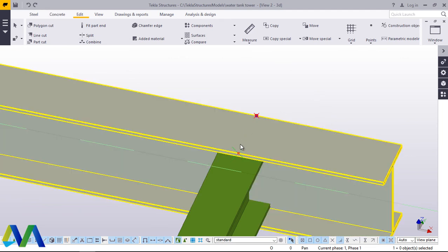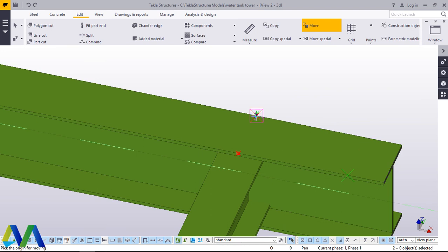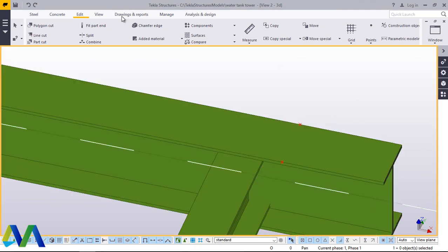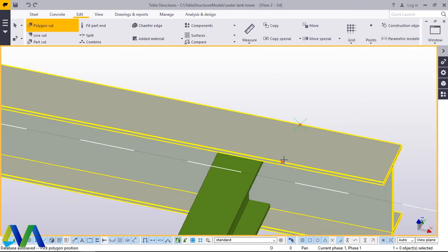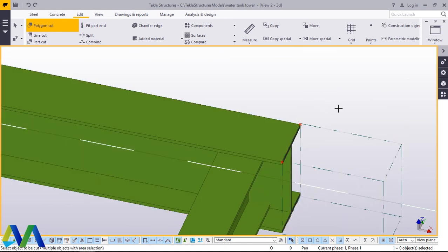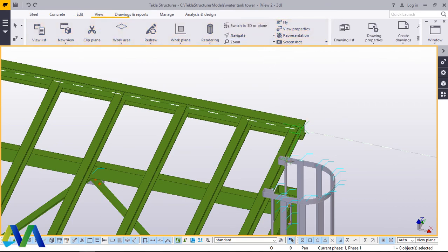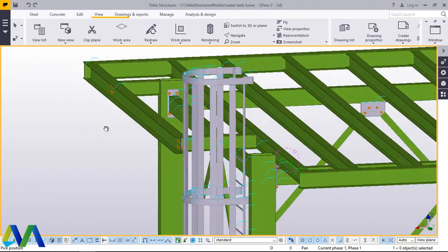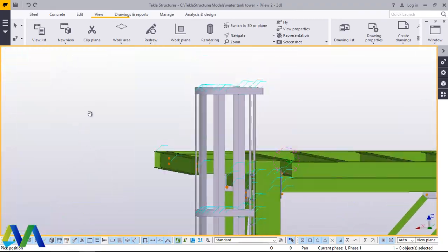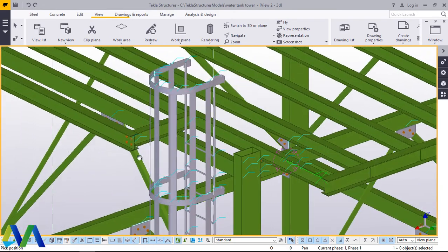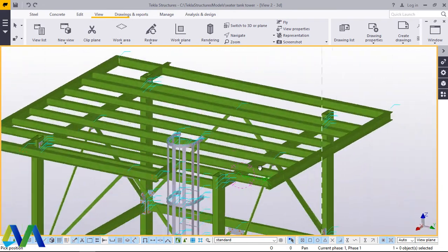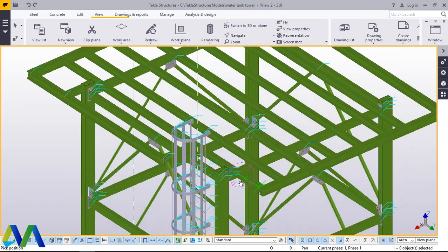Pick that and that. Right click and click move from that spot to that spot by 100. We'll come to edit by polygon, click that, run all the way to that spot, all this spot, and you'd have trimmed that point. Now if you go back to view and come to navigate, rotate with mouse and snap at a point where you intend to rotate the model about, you'll turn this like this. Perfect and right on the positions we intended to see this in.